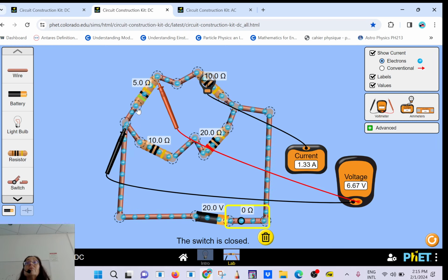Even though a battery cannot provide the AC circuit, you see what's happening to the hot wire. You see how it's plus and then becomes minus and then it's plus, right? So the voltage increases to 170 volt and then it goes to 0 and then to minus 170 and then back to 0, because the hot wire that you have in the plug switches 60 times per second. Okay, so the current is flowing in one direction, then the other direction. So it's going back and forth 60 times in 1 second, and the period is 0.02 seconds.